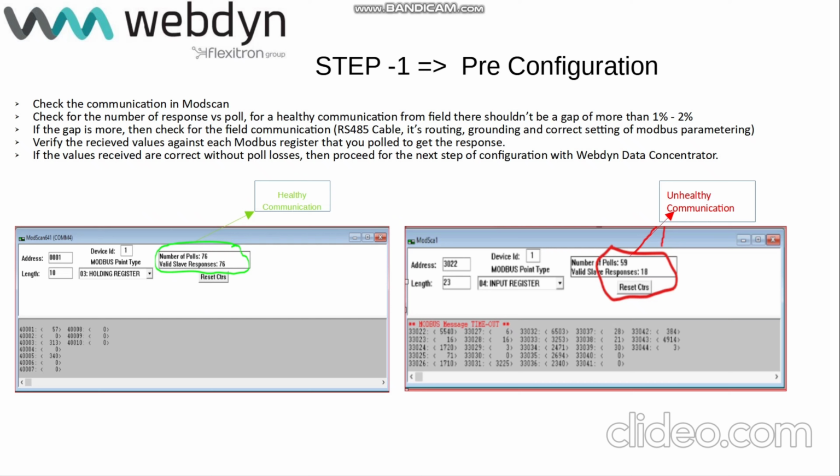And if your cable is crossing and passing by other current carrying cables of AC or DC nature, their magnetic flux interference might create issues in the response, because the data flowing in your communication cables is in bits, carries very low voltage, and might get easily disturbed by any outer magnetic interference.